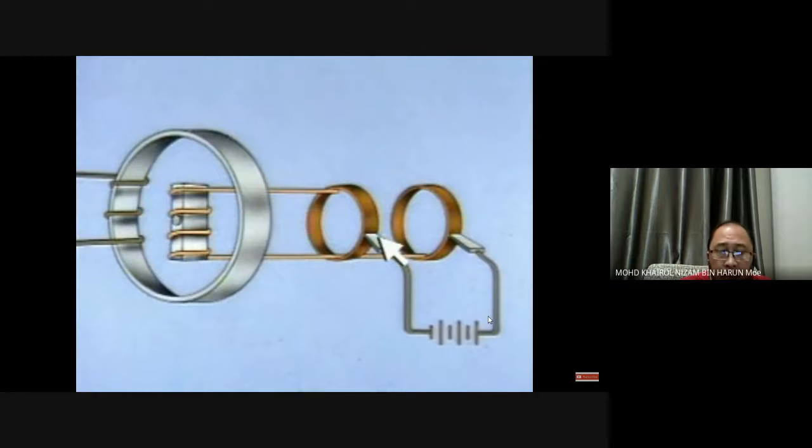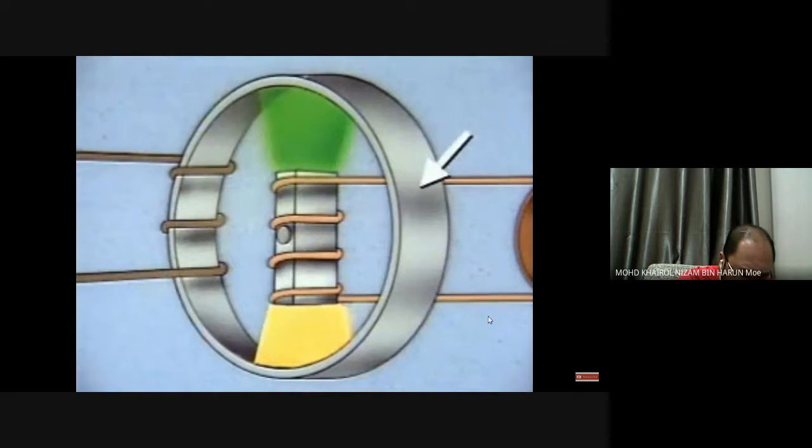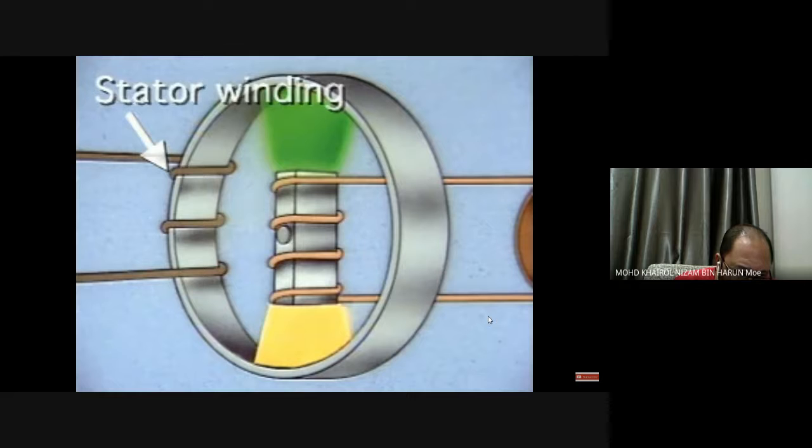Current flows from the negative side of the DC power source through one brush to a slip ring. From there, the current flows to the winding around the rotor core where it creates a magnetic field. To complete the path, the current flows from the winding to the other slip ring, then to the brush, and back to the positive side of the DC power source. The component of the generator that doesn't rotate can be referred to as the stator. The conductor that is wound around it can be called the stator winding. The ends of the conductor are connected to the power system.